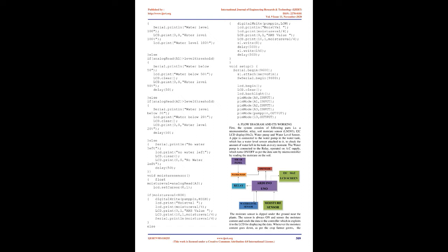drawn for external use. A PV cell consists of P and N type semiconductors. By placing the P and N types together, a junction is formed so that charge can pass through it. The electrons and positive holes from the P and N types are attracted to each other and start to flow to opposite types in the semiconductor. This attraction between electrons and holes is counterbalanced by the electric field.